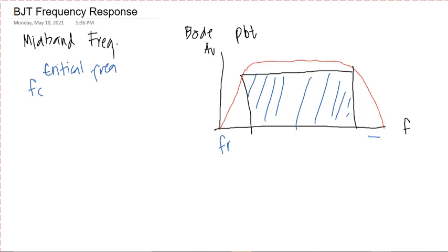In other books it is also called the cut-off frequency. So what is the cut-off frequency? It is the point where our mid-band frequency ends. So here, we have this part and this part. How do we determine it? Based on the highest linear peak of our amplifier response.